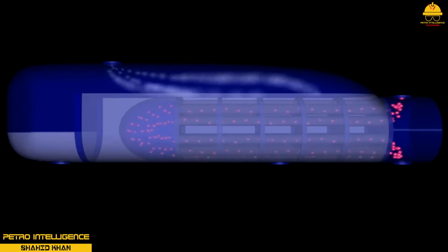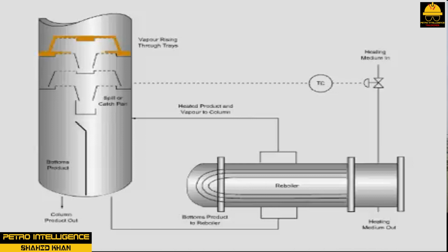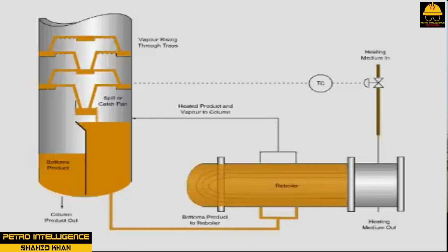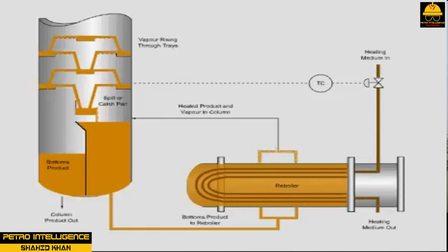An important concept with a distillation column is energy or heat balance. Reboilers are used to restore this balance by adding additional heat for the separation processes. Bottom products typically contain the heavier components from the tower. Reboilers take suction off of the bottom products and pump them through their system. Column temperatures are controlled at established set points.